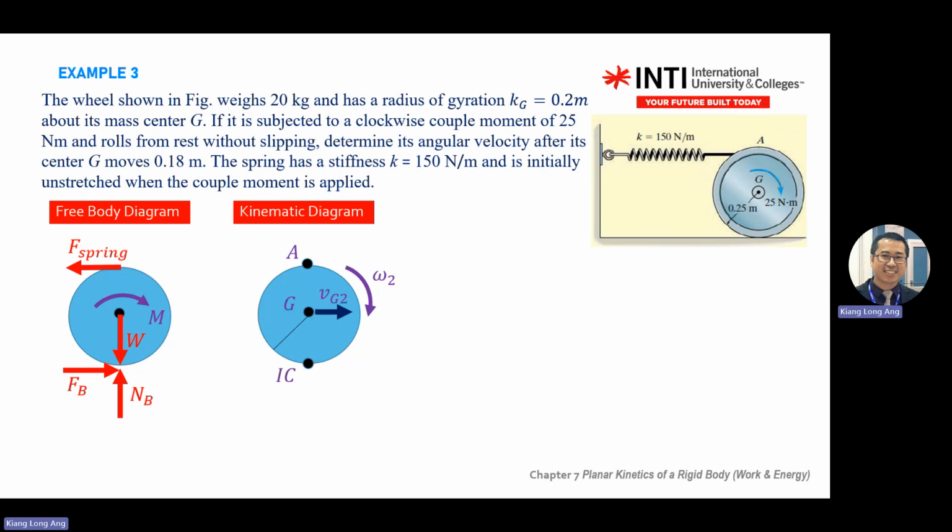Okay, so you have I and IC. Why do I use IC? Because that is the easiest way to find omega. Just put your ruler there. And you know that a round body always moves in one direction, either left or right. So you just draw the perpendicular direction. Move your ruler over here. Draw the IC point. IC is actually your radius. So v equals what? v equals omega R. Rearrange the equation, you find your omega.